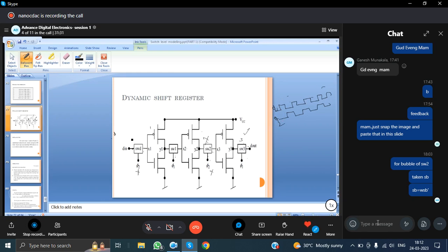First it is latched, and in the next clock cycle the data is shifted. So the data on the input line is latched and shifted on successive clock cycles. All these three stages together are called a shift register.